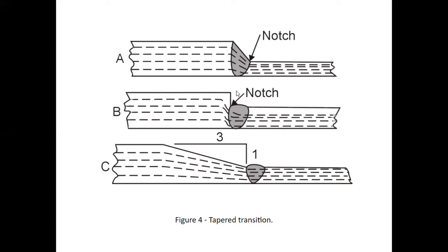So here, example A is an attempt at tapering this out to get a bit more flow of the stress lines. Now they've done definitely some work here. You can see we still have a pretty hard transition here at the bottom, and these inside notches are going to be where the stress is going to cause a fracture. And then this would then fracture right on the outside of this weld, probably down along the weld, and then those pieces would break.